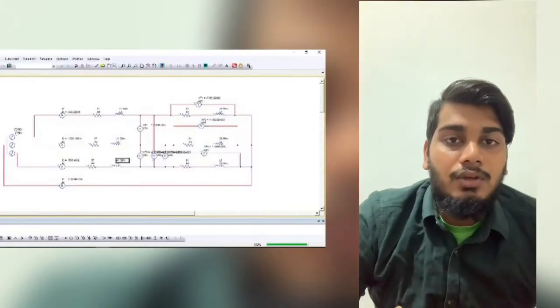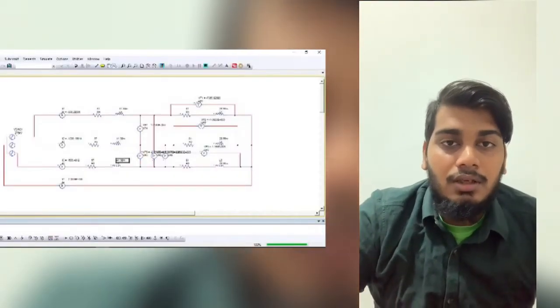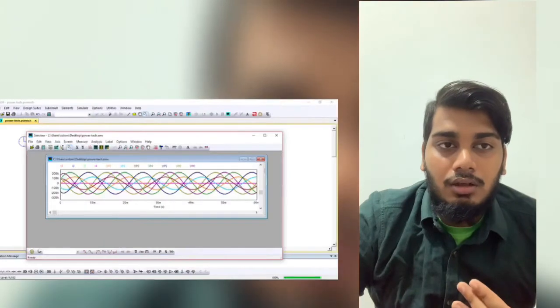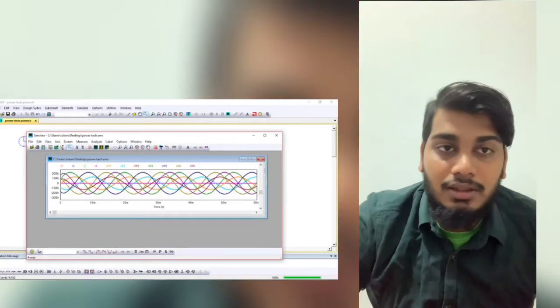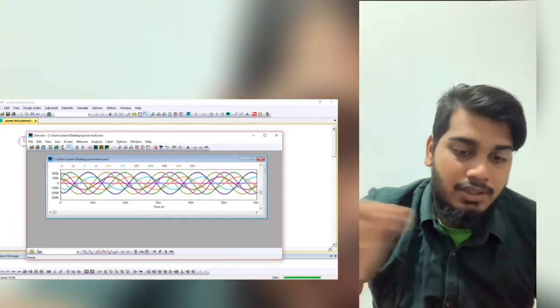After that, we drafted a three-phase Y connected circuit on a piece of paper. After we had done the draft, we used the PSIM software to construct the circuit with all the values that we had found. Next, we need to simulate and record the data and compare it with the calculation that we have done manually.